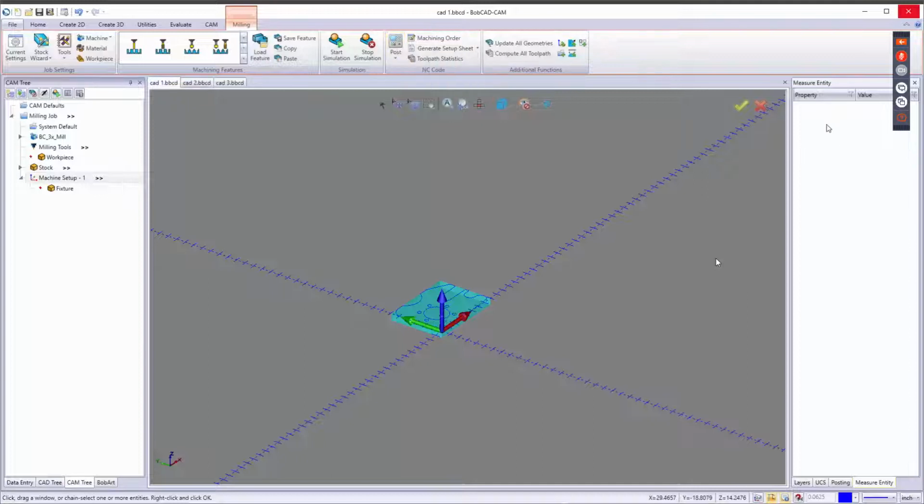That's going to generate your G-code that's going to show up right here or wherever you got it on your screen. I never do a post and save as because I usually like to show the post. I like to see the post. Hopefully you guys know a little bit about G-code, and you'll want to see things showing up as needed in that G-code. If there's not, there's something wrong within either the toolpath or the post itself that we need to get fixed.